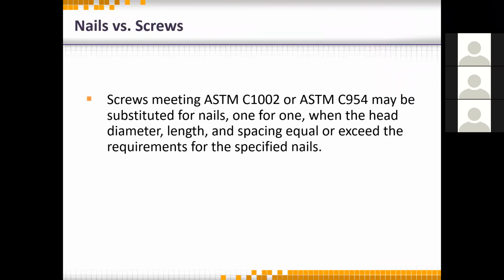For those of us that do wood construction or install wood construction or design it, what UL says is that if the wood wall, the drywall was attached with nails, the contractor on their own can decide to use screws instead if they prefer. Maybe it's faster, I don't know. The owner can say, no, I don't want nails, I want you all to use screws on that. And the architect can do the same. So if it's tested with nails, you can use screws, but the screws have to be the same length as the nail with the same diameter head. If the test was done with screws, contractor or anybody else cannot substitute nails for those screws, okay? So the opposite is not true because we're gonna weaken the system.